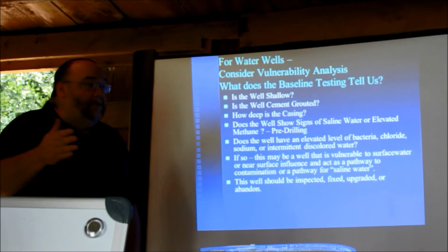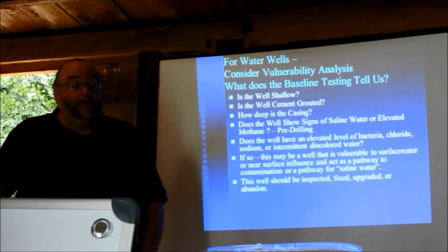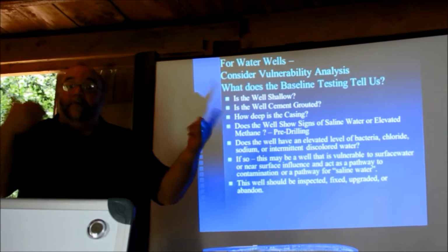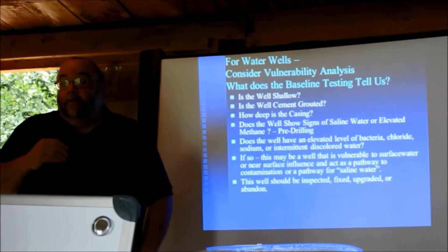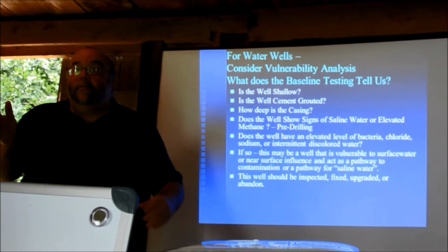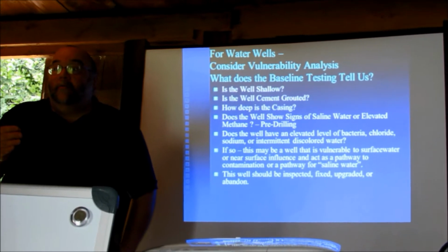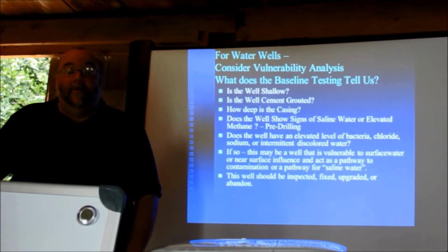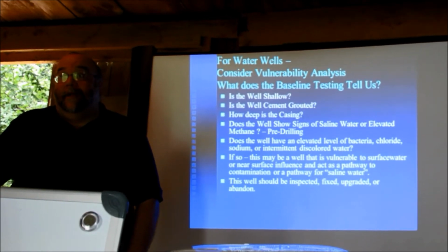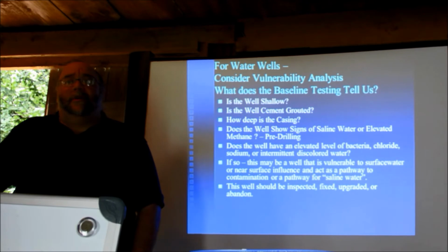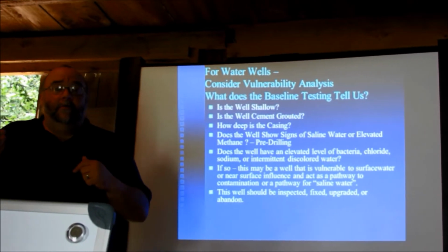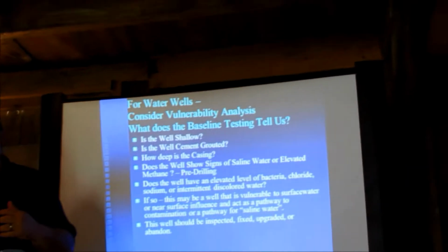Typically, most of the wells in general have methane levels below 2. Definitely below 1. Most of the wells where? In Pennsylvania, northeast. What about Susquehanna County? Well, naturally before drilling, the most methane or the least methane that you've seen? Well, probably the least methane is not detectable. The most is actually saturated. That dates back to reports in the 30s. Saturated at the surface means 28 to 30 milligrams per liter.